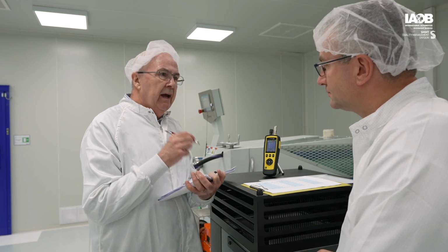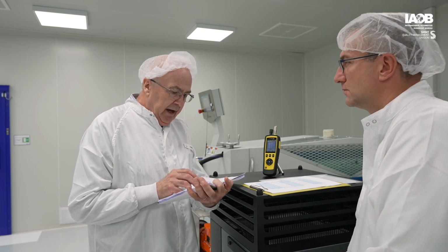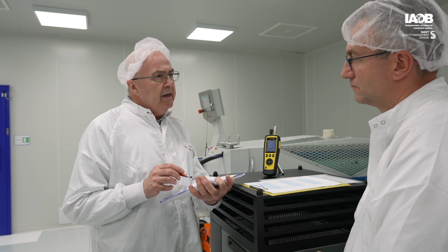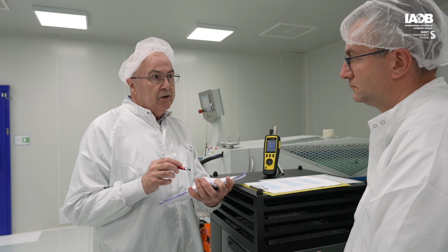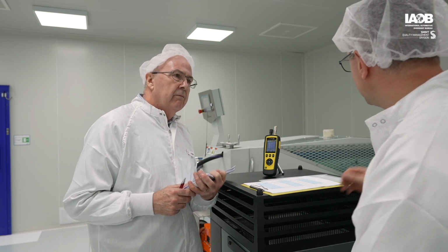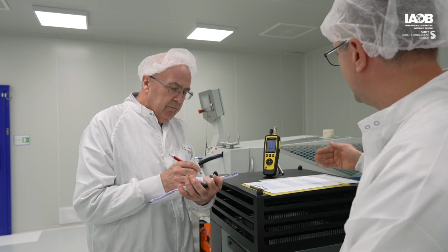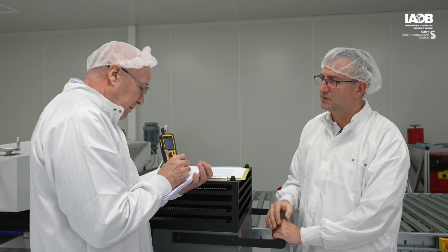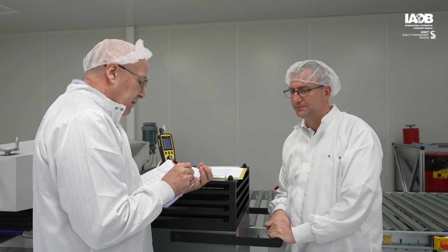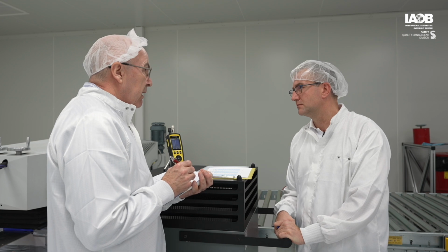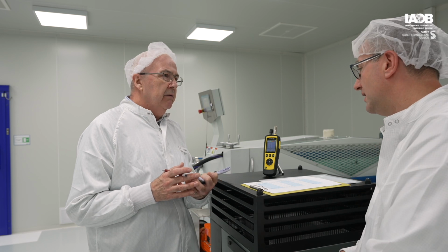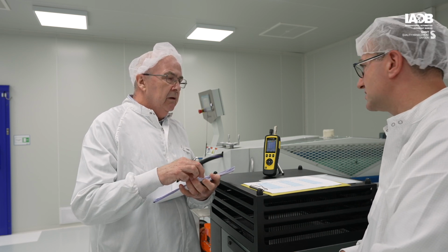So I see through the action you've already taken that you've reduced the risk in the PFMEA from high to medium. Have you got any other actions planned regarding control of contamination within this area? Yes, we have. The next step is that we install on the production row 2.5 meter anti-static bars. This will also be a big help to prevent inclusions and scrap. And what is the timescale for doing that? How long do you think that's going to take? Next week. Oh, this soon? The installation is already ordered, and next week the bars will be installed.